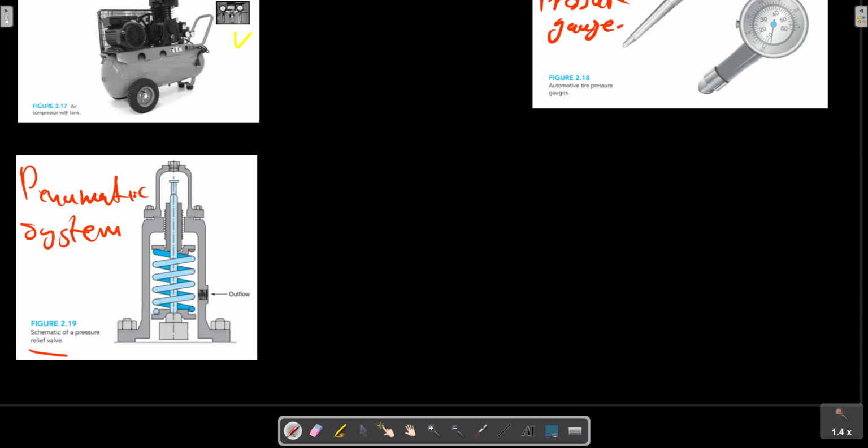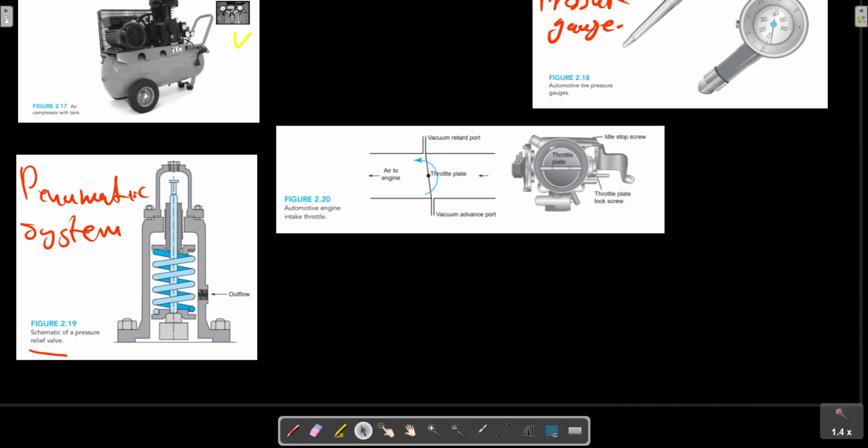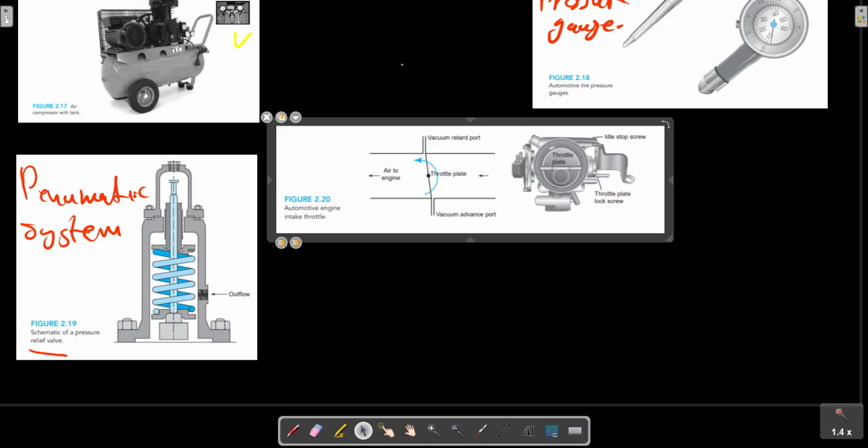When a throttle plate in an intake system for an automotive engine restricts the flow, as in this picture, it creates a vacuum behind it that is measured by a pressure gauge sending a signal to the computer control. The smallest absolute pressure occurs when the engine idles and the highest pressure occurs when the engine is at full throttle. In this picture, the throttle is shown completely closed.